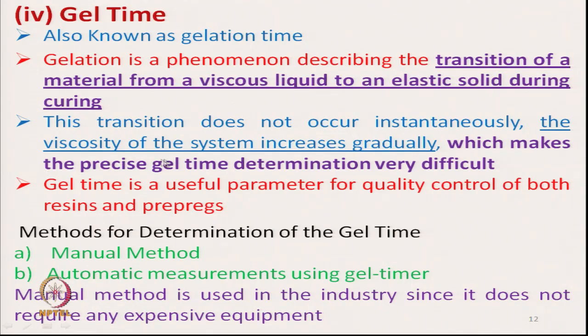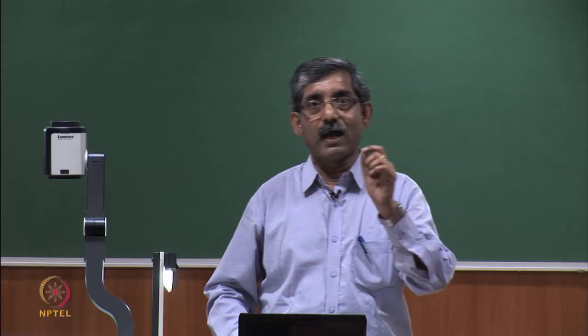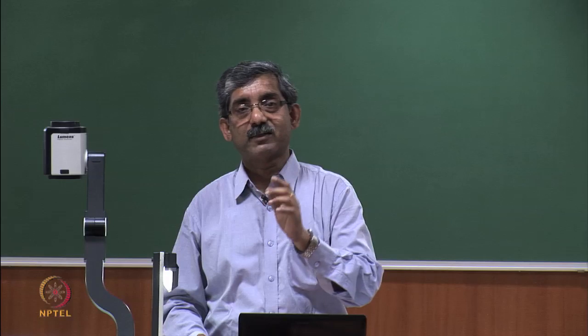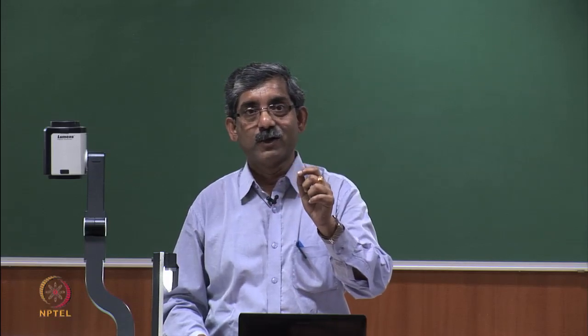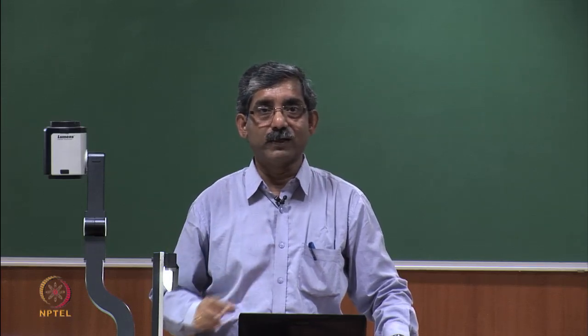The viscosity of the system increases gradually, which makes precise gel time determination very difficult, because this is taking place gradually, it is not at a certain point. So, for precise measurement, we have to do repeated tests manually.